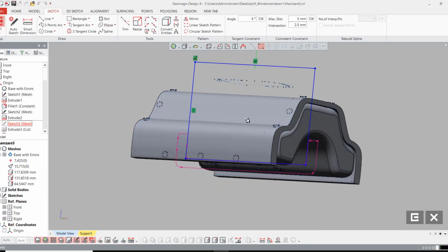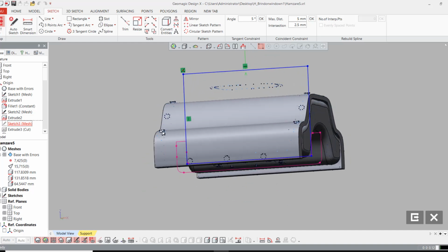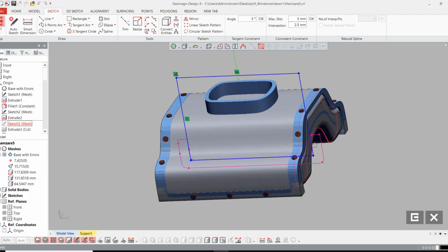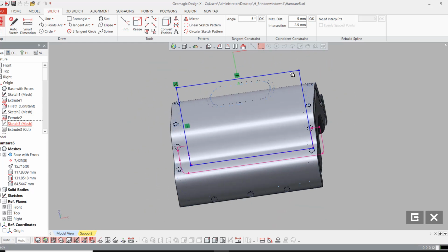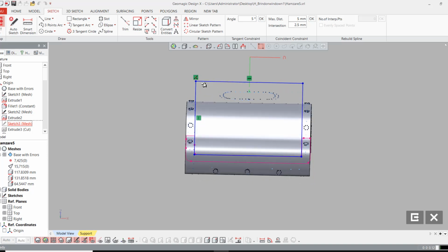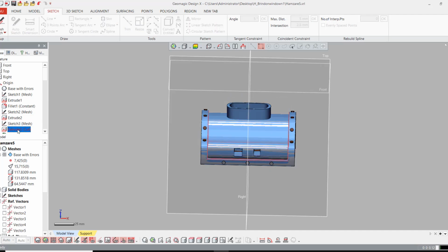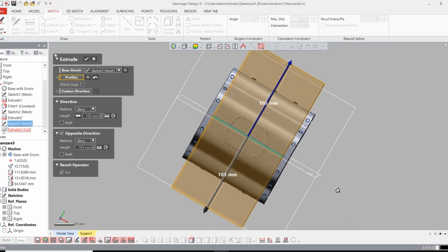After that we will extrude cut this profile from this front view, and for that I used a mesh sketch, and I extracted this profile. We can see it in the pink line, and we can create these lines to make the extrude cut. And the extrude cut will cut this part from the center.